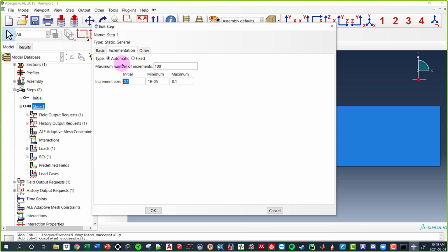Now, if I place a load on the beam of 200 kilonewtons, our step size is still 10%, so each increment will be 10%. Of my 200 kilonewtons, 10% is 20, so it's going to go 20 kilonewtons, 40 kilonewtons, 60 kilonewtons, and so on. That's one of the last things I want to make clear when dealing with incrementation.